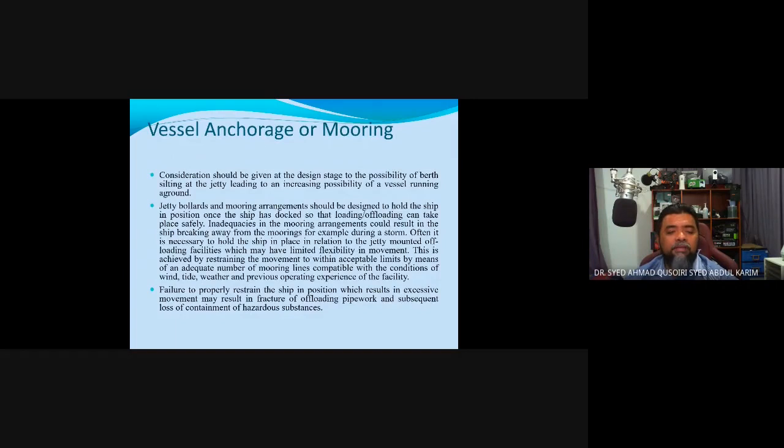Consideration is to be given at design stage for the possibility of burst silting at the jetty, leading to an increased probability of vessel running aground. The design of the jetty should take this into consideration. When silt starts to build up near the jetty, this can make the vessel get stuck at the jetty. So this can be a tremendous hazard.